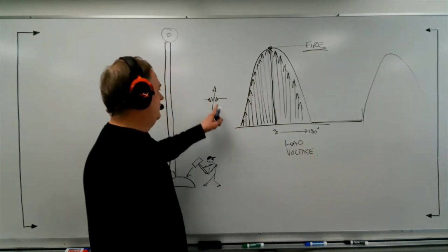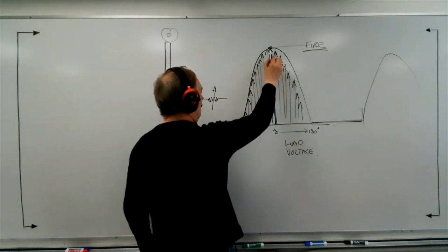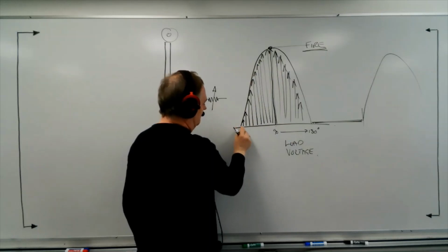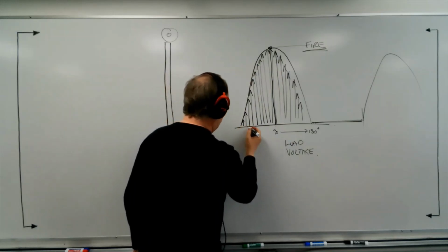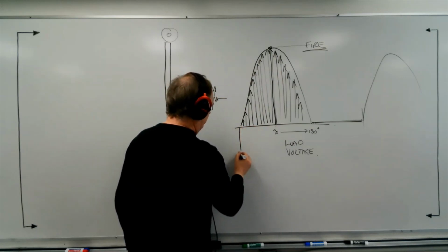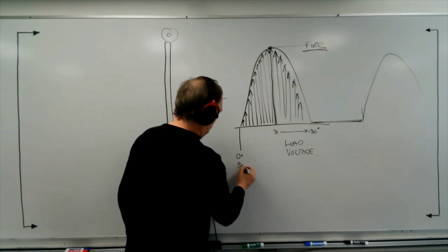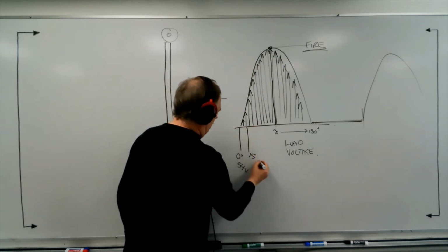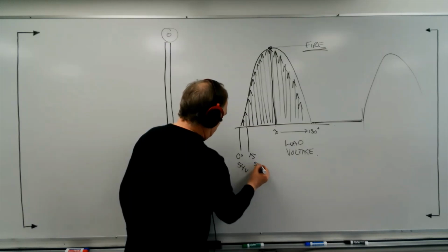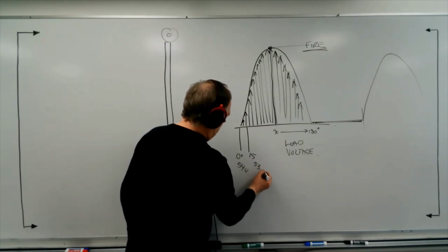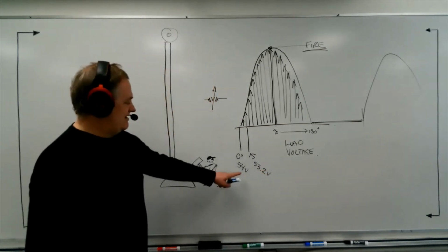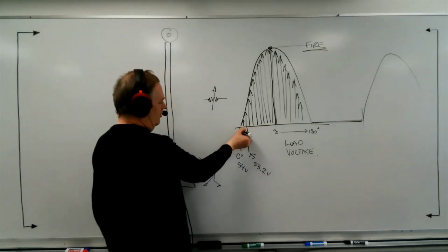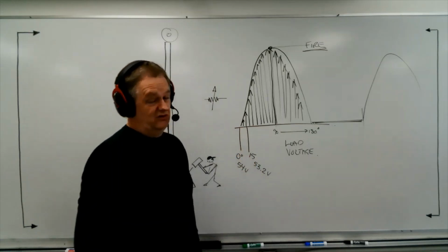Now, your option is to reduce the resistance, and that way you'll hit your firing current level sooner and sooner and sooner. And if you lower your resistance low enough, you can virtually fire all the way to 0 degrees. Now, practically speaking, I want you to remember that there was 0 degrees, which was about 54 volts, and 15 degrees was the angle that I showed you. And the voltage at 15 degrees was actually 53.2 volts. So you only lost about 0.8 of a volt for having 15 degrees. And so we don't worry much about trying to make trigger circuits that come earlier than 15 degrees, because that's just simply not enough voltage to make a difference.